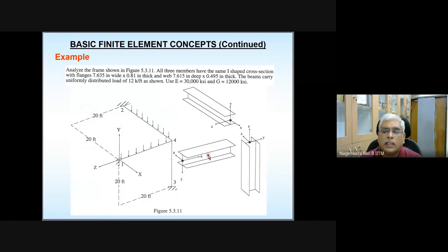And please note that at this stage, whoever is doing it using pen and paper, now you can realize you need to adopt some software like MATLAB or Mathematica to solve this problem. Even for this problem, you need to adopt it, because to multiply even the reduced stiffness matrix you require working on 6x6 matrices. If you use MATLAB, it won't take much time.